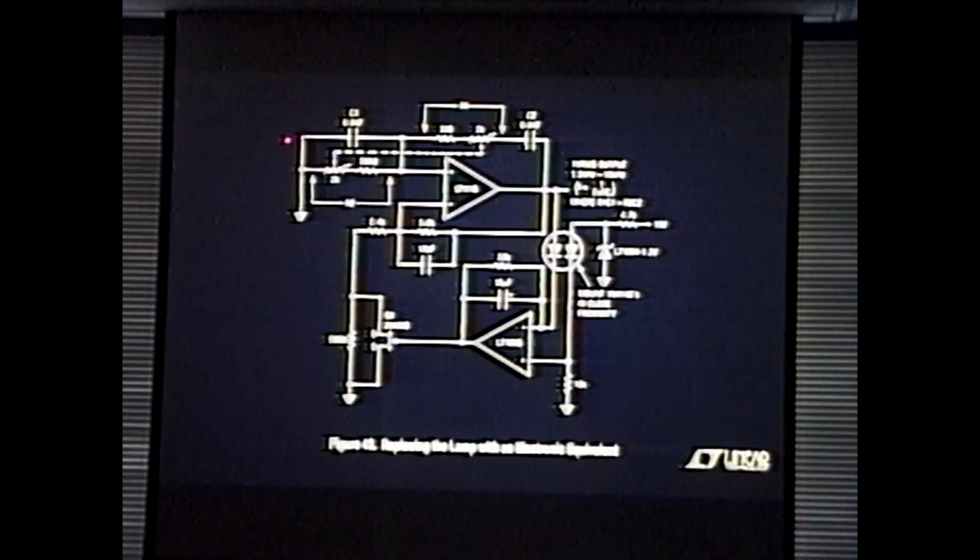You can see the outline of the basic circuit up here. That's the Wien bridge up there, as before. The lamp was down in here. Now it's gone. Okay. What do we got? We have an electronic version of the lamp. And the way it works is, in this case, we sample the positive output peaks of the sine wave.